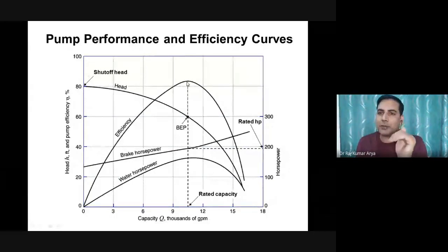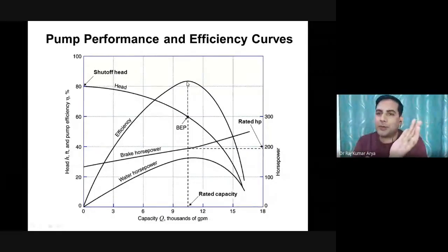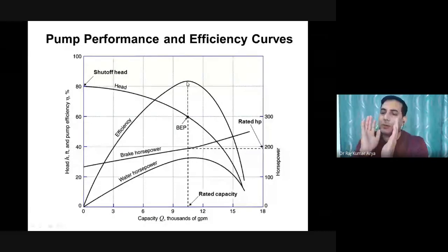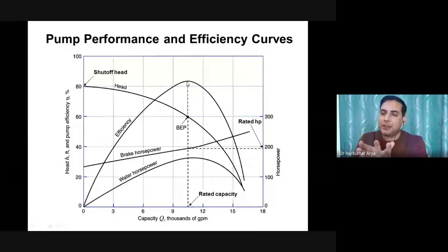If you increase the diameter of your outlet further, you will not be able to discharge the fluid; nothing is coming out from the pump. Your pump is working fine, but the diameter has increased too much and the discharge has become too high, so no energy, no head can be provided to the fluid.